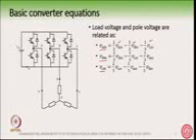These are the voltages which are appearing between the points A and N here. We have derived this equation, and this VAO is the pole voltage. O point stands here and VAO is the pole voltage.